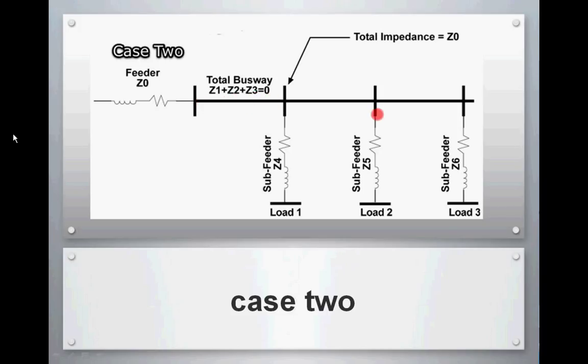So now we don't have an arc flash label for each individual plugin, but we have an arc flash label for the whole bus duct, and we have then one, of course, arc flash label for each individual panel, which is going to be different from the other ones, and it's going to be the worst possible case of the 2 scenarios. Okay. So that's the way that I recommend doing this.